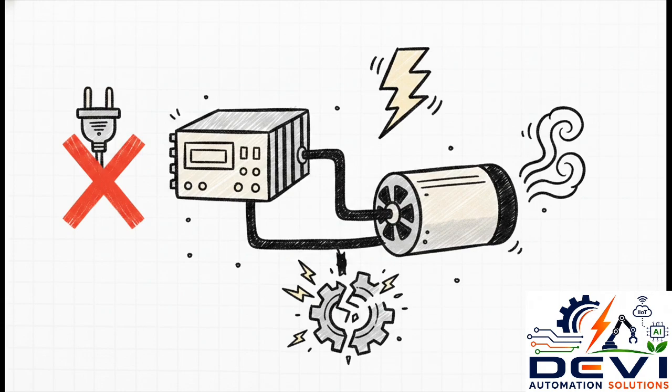If you skip configuring the drive, you aren't just risking that the motor won't turn on. Without dialing in the correct parameters, that motor can immediately throw a fault, run terribly inefficiently, or, worst case scenario, suffer permanent mechanical or electrical damage. And man, nobody likes the smell of burning expensive motor windings. You just can't treat a VFD like a simple plug-and-play gadget.